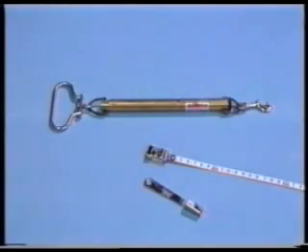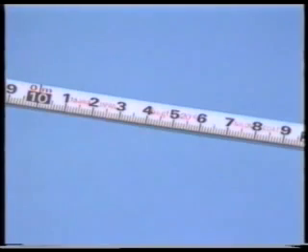The tension correction need only be considered when using steel tapes where high accuracy is required. The steel used to make steel tapes is elastic in nature, and if the tape is pulled, its length will change slightly depending on the amount of pull or tension applied to it. To allow for this, all steel tapes are manufactured and calibrated with a standard tension applied.